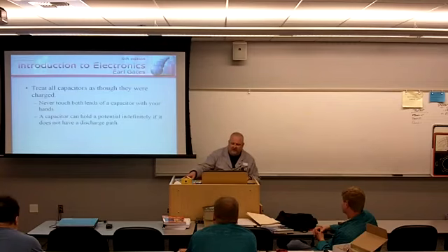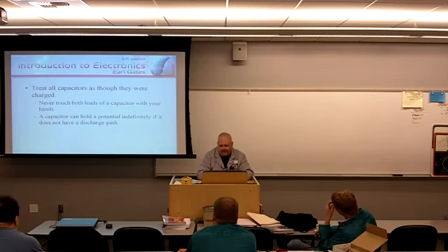Treat all capacitors as though they were charged. Never touch both leads of a capacitor with your hands.